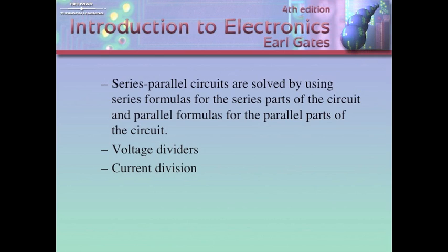If I measure the voltage between here, this point, let me label these nodes here. I'll put 4 nodes here. One at the top is A, B, C, and D. If I measure the voltage between C and D, I want to get 5 volts. Agree with me? If I measure the voltage between B and D, and I want to get 12 volts, how many volts are going to be across this resistor alone? Very good. This will be 7 volts.